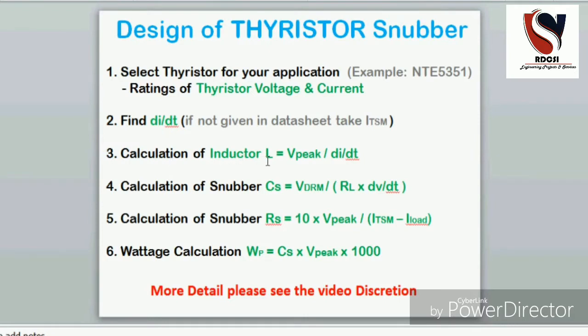If it is not given, then you can take the ITSM, which is available in the data sheet. The third one is calculation of the inductor. When you connect a motor load or any inductor for filtering purposes, you can find out the L value using this equation. The fourth and fifth steps are used to calculate the snubber resistance and capacitor value. The equations are given here. According to these equations you can find all the parameters in the data sheet, and you can calculate the values of C and R.